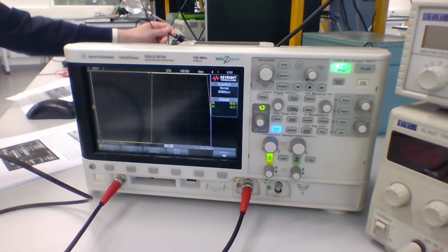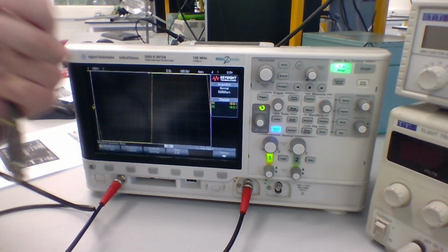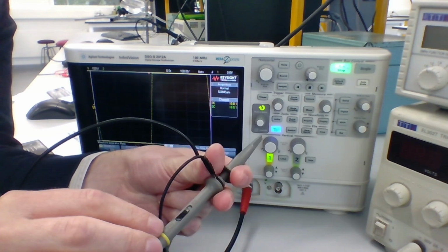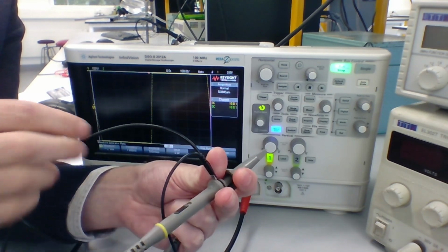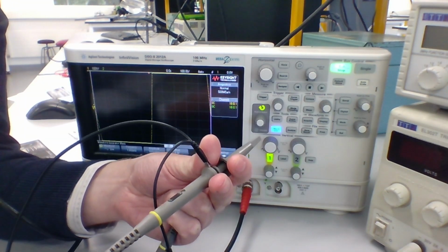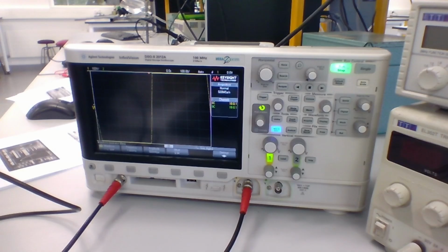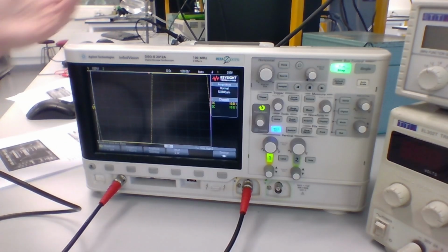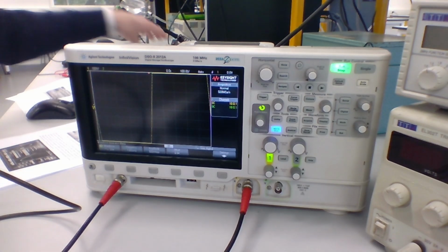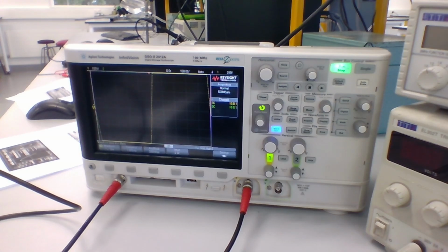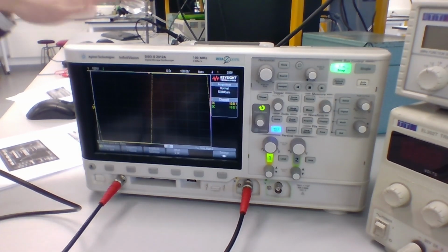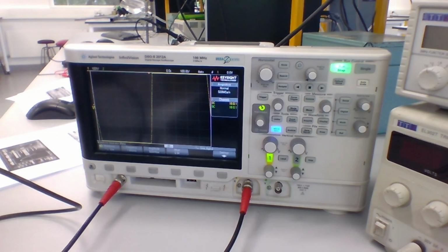If we look at one of our oscilloscope probes, you'll see on the front here, this has a little switch with two options, 1x and 10x. This sets the probe's attenuation factor. Basically, if it's set to 10 times, it reduces the amplitude of the input voltage by a factor of 10. If it's set to 1x, it doesn't change it at all. This can be useful for looking at voltages that are quite large, relatively speaking. But we also need to tell the oscilloscope that we've changed that setting, because the oscilloscope doesn't know what that switch is on. Some oscilloscopes and some probes are a bit smarter about it, or have some active attenuation there, and will automatically figure it out. Most of them are set manually though.